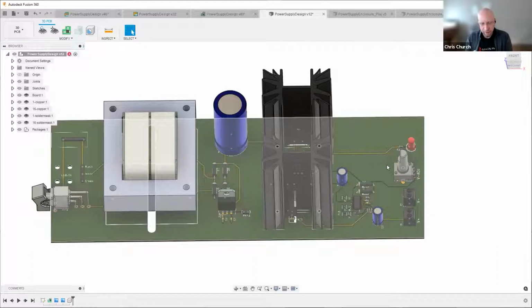When we're doing that, the challenge always becomes how we actually repeatedly do those bends and do that height placement, et cetera. So just like we would do a shim with that transformer, if we had needed to, we can do the same thing with the LED, and you can even model that up. One of the very common things out there is to use standoffs with LEDs. There are a lot of them available if you need to set it at a certain height. You can bring in that model, add it to your EBOM, and then that way we can see it already part of it. When you upload that ODB++ file out of Eagle to us, it'll automatically bring that in.